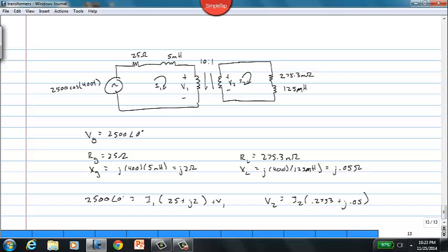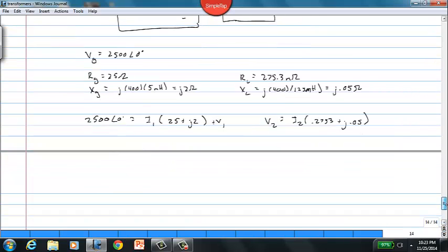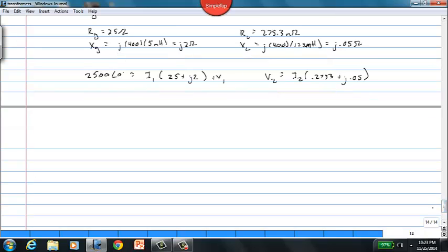You'll notice that when doing ideal transformer analysis, we don't include the inductance of the primary and secondary coils. That's built into these voltage assumptions here, and it's one of the assumptions of the ideal transformer, that this thing doesn't actually have any inductive reactive loss. Obviously not true, but a simplification.